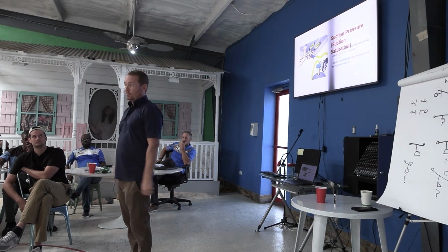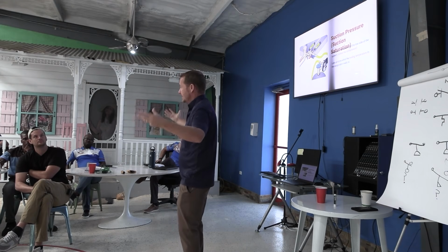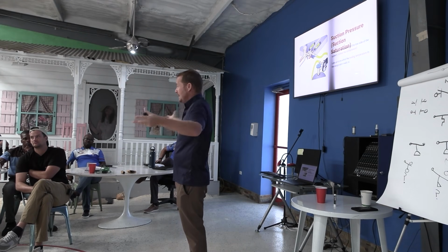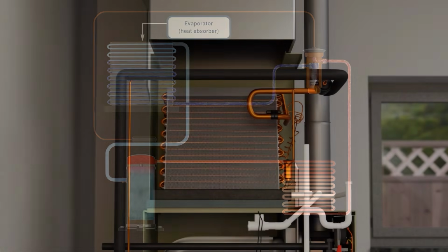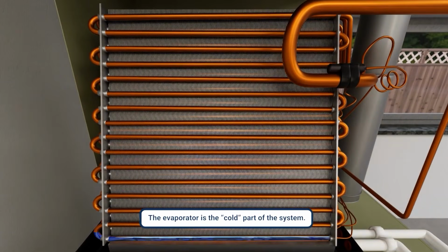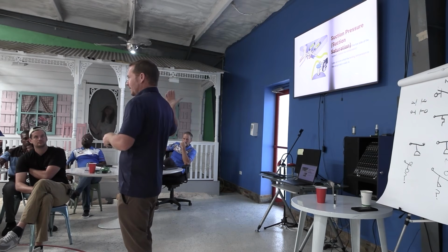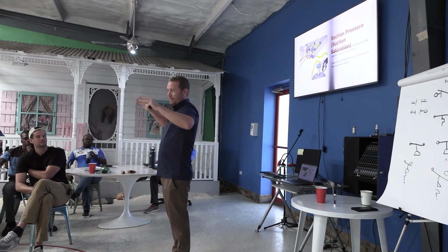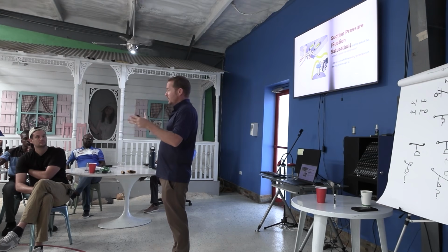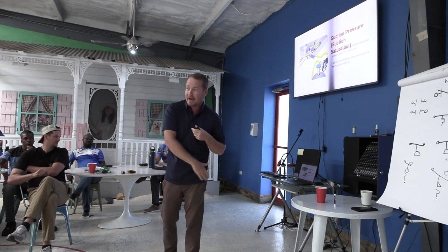No air's going over the evaporator coil anymore, right? And that evaporator coil relies on that heat from the inside to keep that suction pressure up, right? It needs heat. It needs to be fed with heat. The evaporator is the heat absorber. With this group, I'm not going over the basic refrigerant cycle. We're doing that with the apprentices, right? So if you're like, I don't know what you're talking about, we'll go over it again this evening. But for you guys, you understand, the evaporator is the part that absorbs heat. It picks heat up. It's the heat absorber. And so as soon as you get a sheet of ice on that sucker, well, now you've ruined its ability to pick up more heat. So now that suction pressure just dives on you.